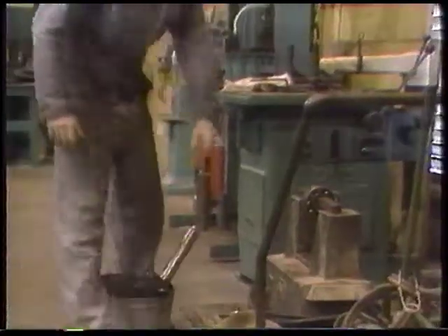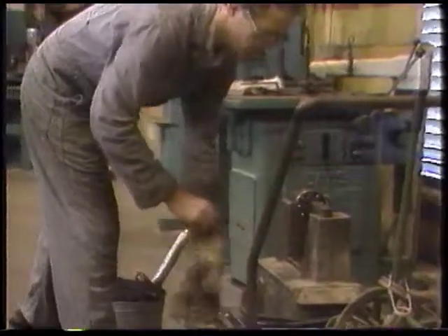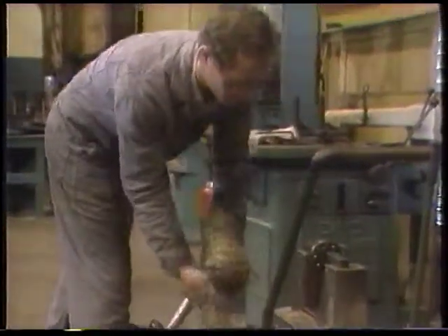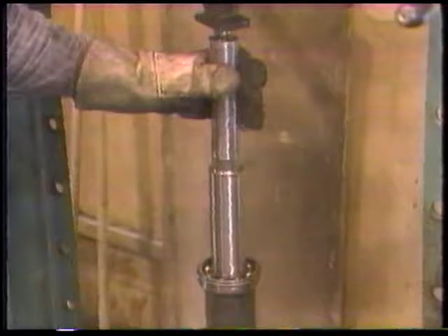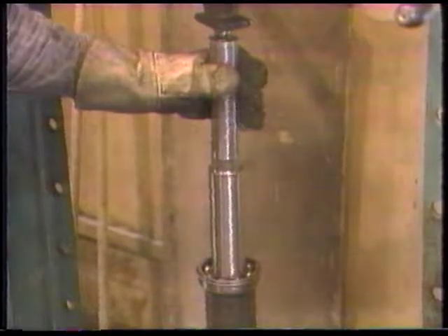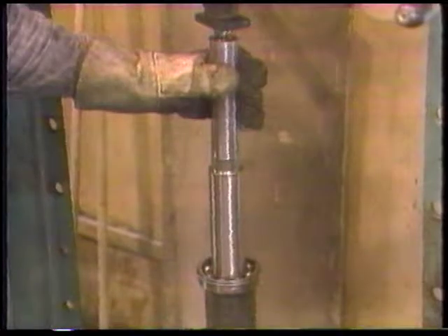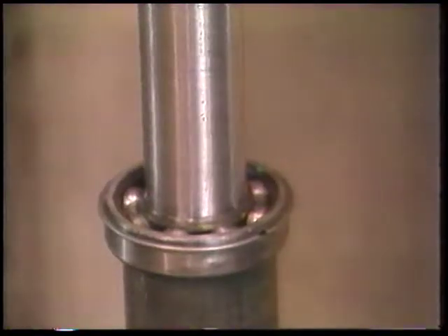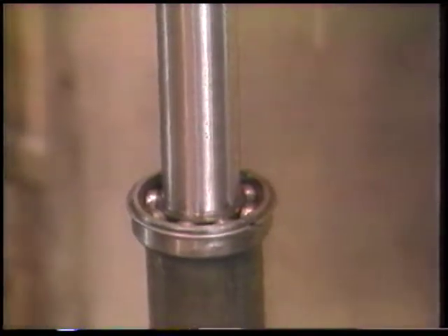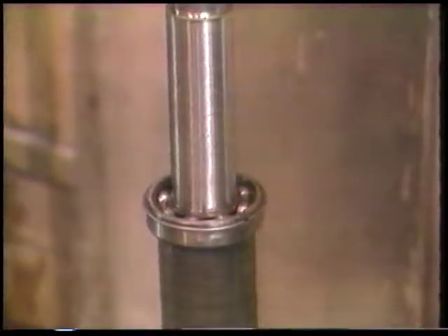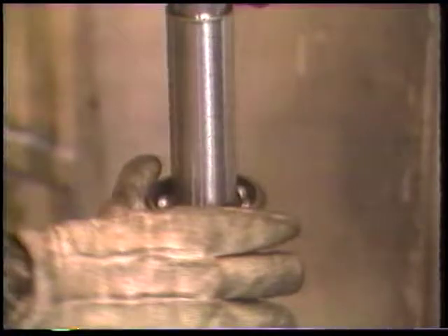Once you're ready to install the bearing on the shaft, work quickly. The temperatures of both the shaft and the bearing will equalize quickly. Since a bearing will sometimes move as it cools, make certain it's kept in place until the temperatures have equalized completely. Sometimes a shrink fit will expand the inner ring, reducing normal operating clearances and causing the bearing to bind. Make sure the bearing rotates smoothly after it is cooled.